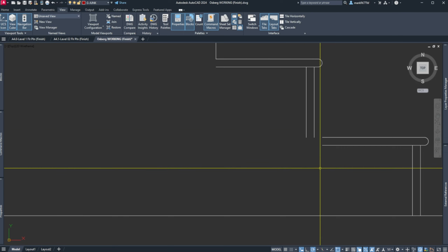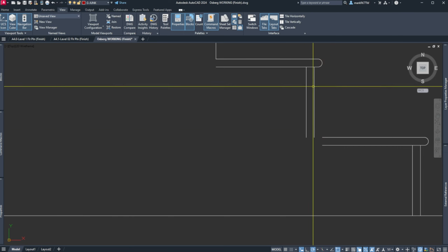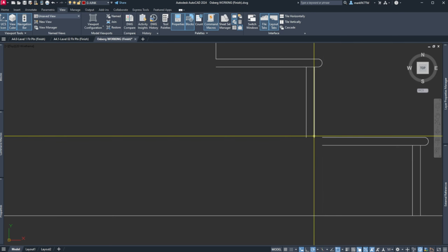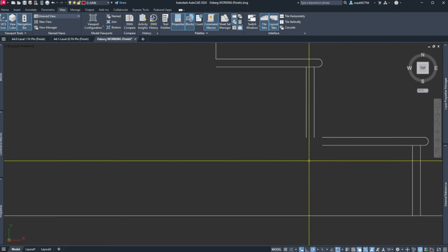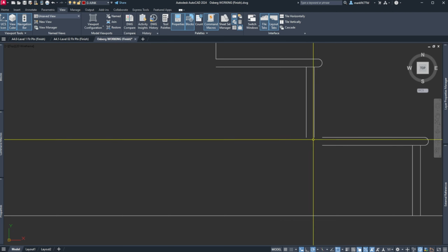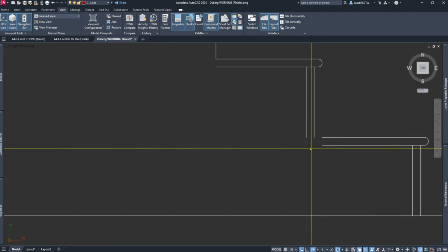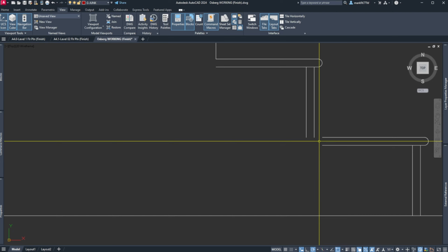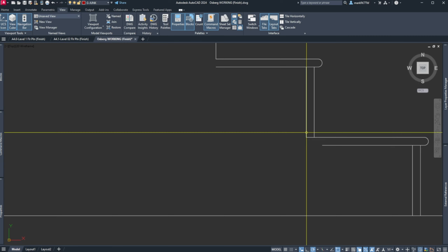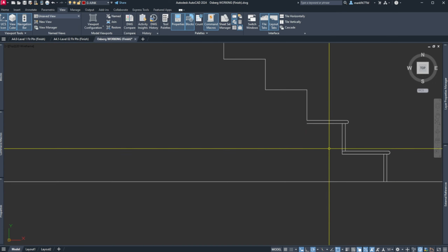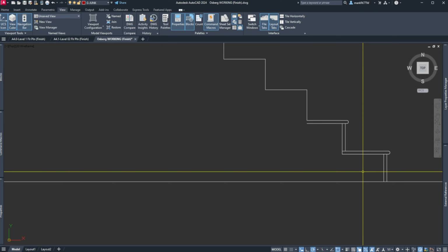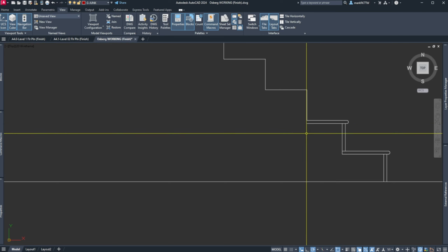Now I want to figure out how do I want to build it. I usually like this piece to land on this one. I don't know that there's a whole lot of difference, but it seems to be less dust. So when the crack is down, then you get more dust in it. So I'm going to just chamfer. My distance is set to 0 to there, and then chamfer that to there. Now I've got this started. And so I need just that last bit right there.